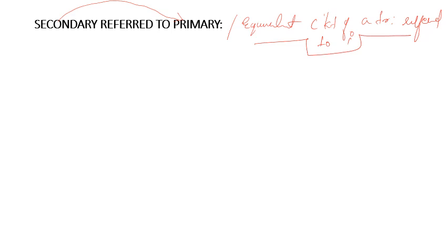So first we can draw primary winding resistance R1, primary winding reactance X1, secondary winding resistance R2. Here if we are transforming the secondary side to primary, then it will be known as R2 dash, and similarly secondary winding reactance X2 dash. Dash means which is coming from the other side. 2 means secondary.